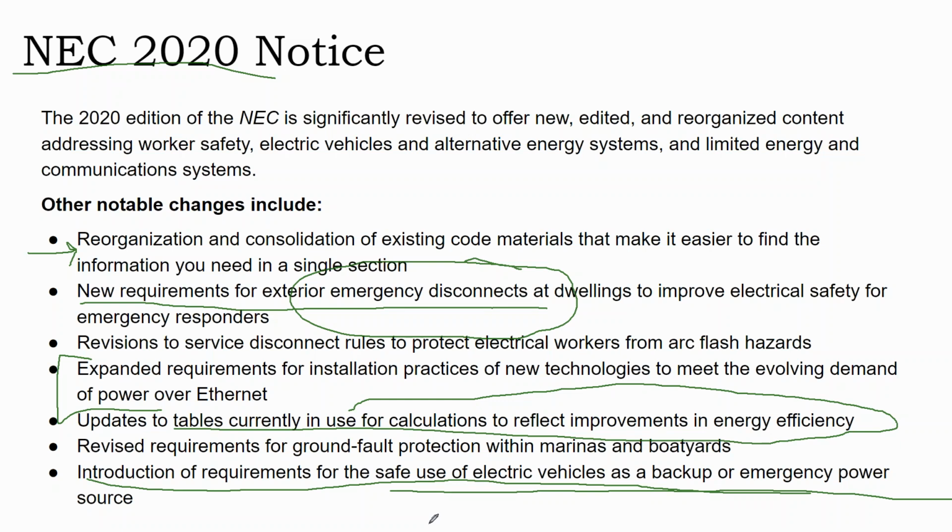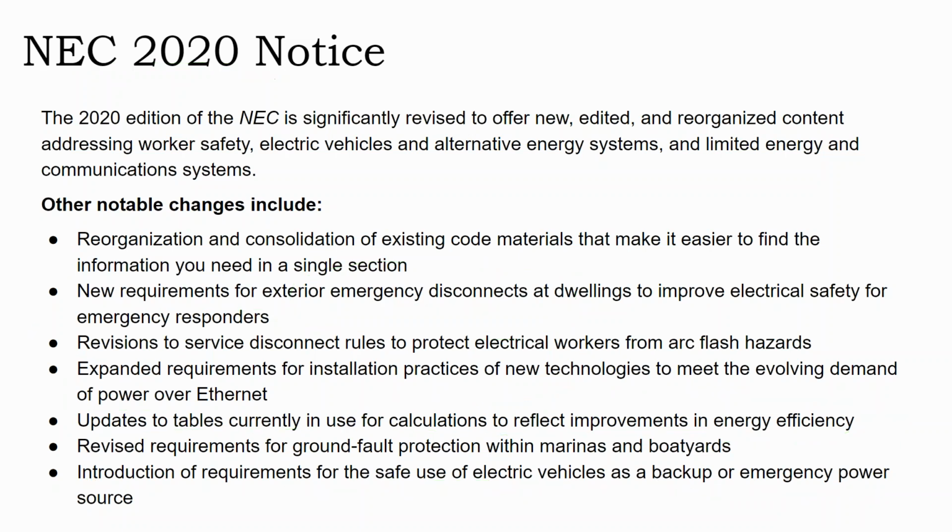But the big thing was that your batteries had to be listed for use. And so could batteries intended for an electric vehicle actually be wired up to a home and used for home safety load? That is something that International Building Code has allowed, but not National Electric Code, which took a more kind of murky response on it. So now we see permissions to use electric vehicle batteries in the building starting to come in. So that's important because electric vehicles are the number one source of batteries, much more so than on-site storage, even though you could argue it would be better for the battery to stay in one place.